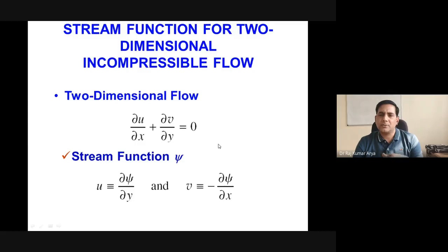And there we have also identified how we identify the dimensions of the flow, whether it is one-dimensional or two-dimensional flow. In that case, you are just finding the derivative of, let's say, your velocity vector with respect to your x coordinate, y coordinate, z coordinate, or sometimes even a time derivative. So based on that, you can tell whether it is steady or unsteady. Steady means your time derivative must be 0. And if you are talking about two-dimensional, you would have only two derivatives which should be non-zero. The rest of the derivatives must be 0. This derivative could be either in the x direction or in the y direction. Correct?